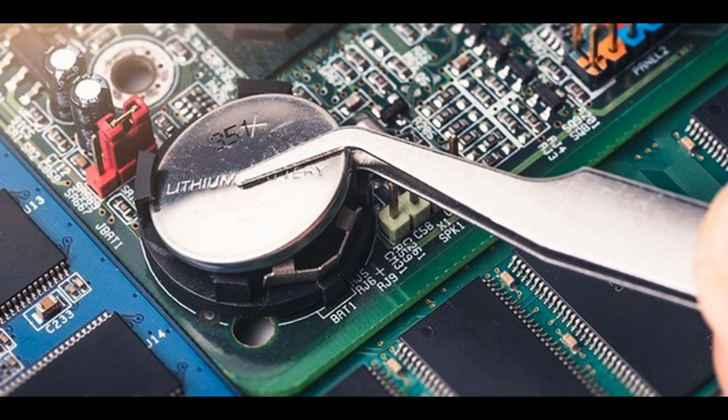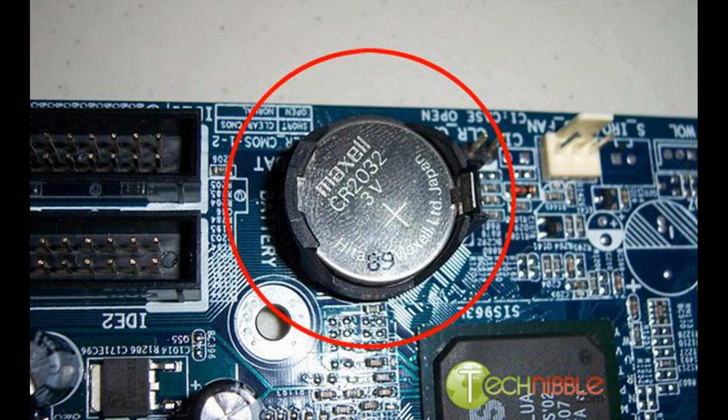The operation of a metal oxide semiconductor field effect transistor, MOSFET, relies on the modulation of the conductivity of a semiconductor channel between the source and drain terminals, controlled by the voltage applied to the gate terminal. MOSFETs can be broadly classified into two types based on the doping of the semiconductor material: N-channel MOSFET, NMOS, and P-channel MOSFET, PMOS. Here's how MOSFETs operate.